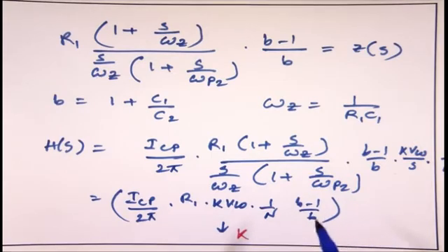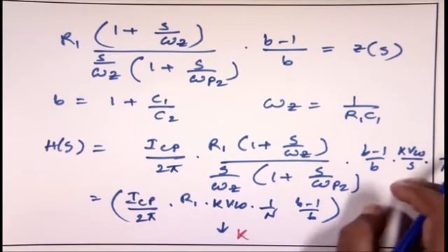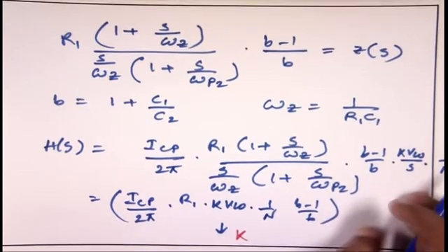In the filter it is actually second order. So always keep in mind that whenever your filter order is some n, your total PLL order will be n plus 1. If the filter order is 2, your PLL order will be 3. So it is a third order PLL, because of the K VCO by S, because there is a pole at the origin.